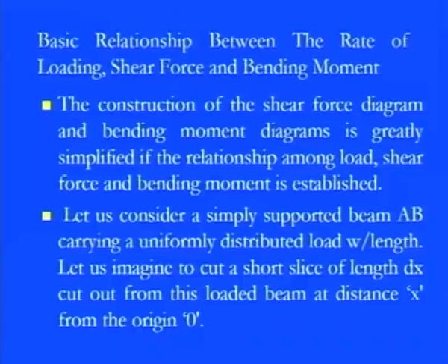So under these load conditions, what is the real impact, and what are the mathematical relations between the applied force and the resultant shear forces for individual sections, and the bending moments in those particular sections? Now we would like to set up the relations, but it depends on what kind of loading it is: point loadings, or a UDL, the uniformly distributed load, or a non-uniform distributed load.